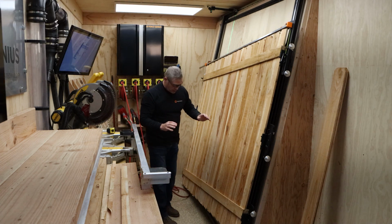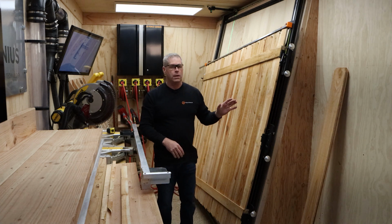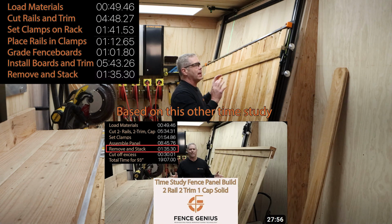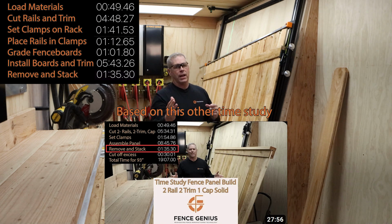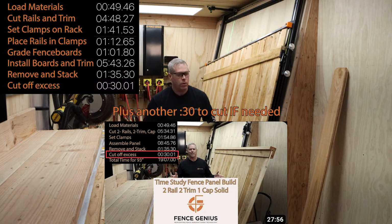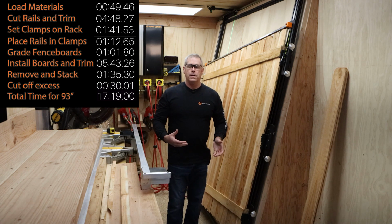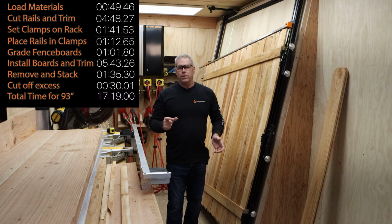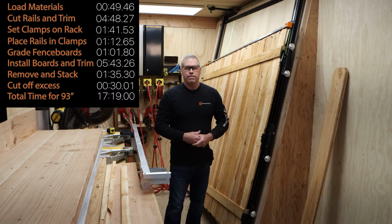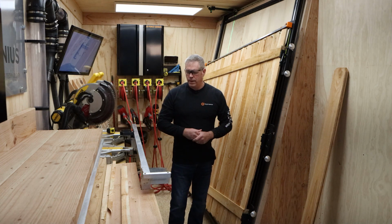Now, the time study on that is done, the actual fabrication. I'm going to add another 1.5 minutes for the amount of time it takes to take it out of the rack, bring it out, and run a saw down this bottom. What I'll do is use a 2x4 as a spacer, and the offset of my saw blade is another 1.5 inches, so I have a 5-inch bottom reveal. That way it's continuous throughout the whole fence system.